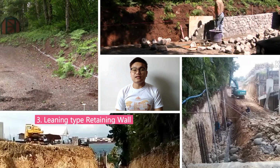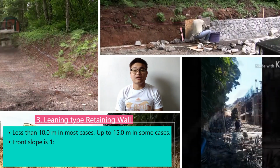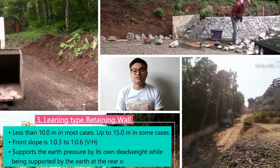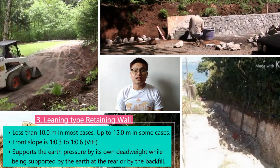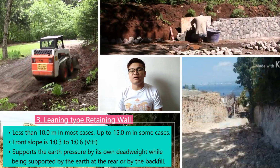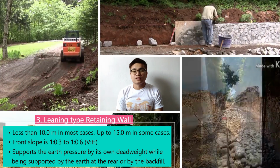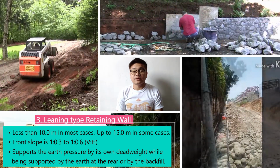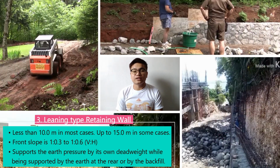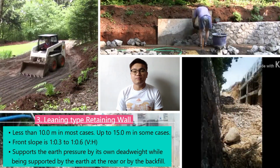Number 3 is leaning type retaining wall. In most cases, the height is less than 10 meters up to 15 meters. The front slope is about 1 to 0.3 up to 1 to 0.6 vertical height, the same as the front slope of the stone or block masonry retaining wall. These leaning type retaining walls are used to support the earth pressure by their own dead weight while being supported by the earth at the rear or by the backfill.